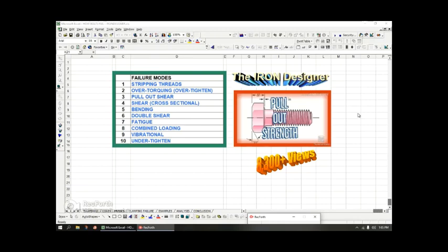You have just single plane shear, which is cross-sectional to the axial load. So now you have axial load stress, and you also have perpendicular to that shear load stress, and that could be bidirectional. So you'd have to find the resulting vector. You also have bending on the bolt. So in some cases you may have a cantilever connection and the bolt is in axial stress, and additional axial stresses are applied to the bolt as a result of, say, cantilever bending.